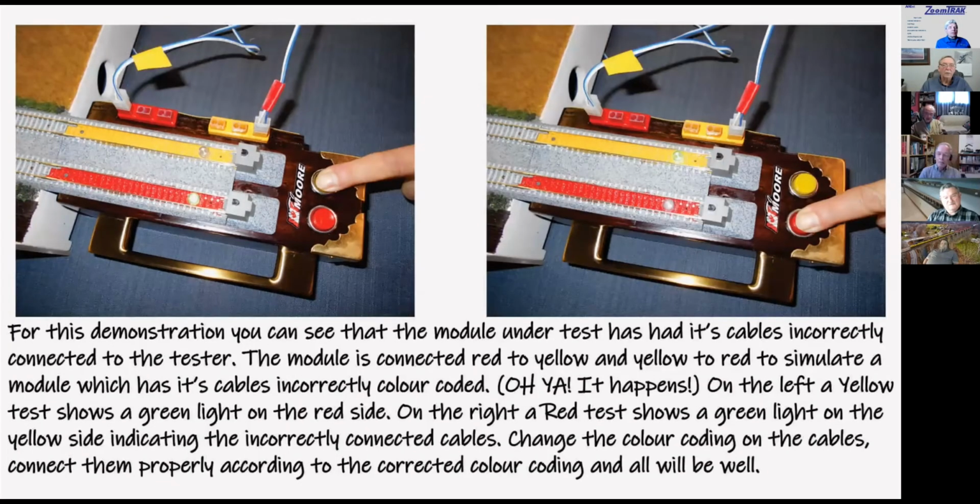For this demonstration, you can see that the module under test has had its cables incorrectly connected to the tester. You can see the yellow cable into the red socket and similarly the red cable into the yellow socket. The module is connected red to yellow and yellow to red to simulate a module which has its cables incorrectly color-coded. And I know, yeah, it happens.